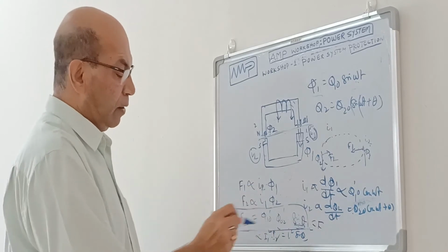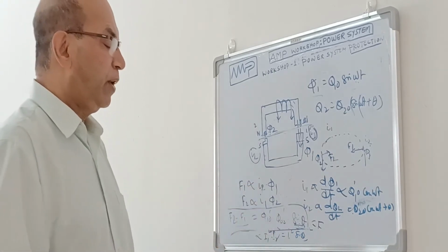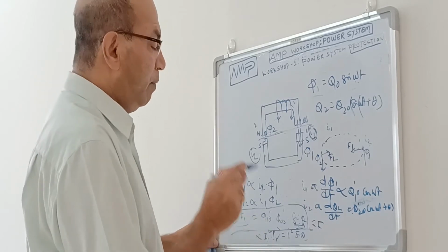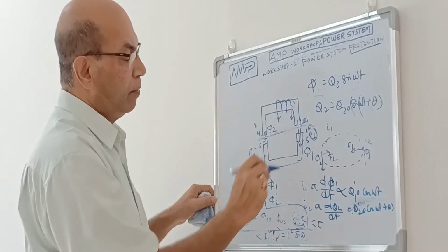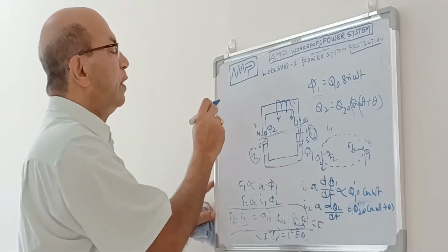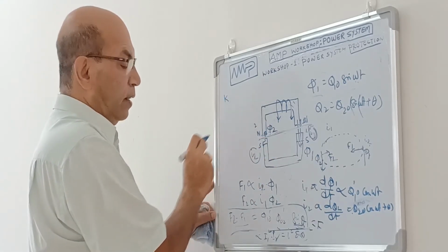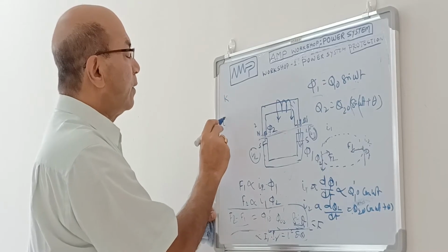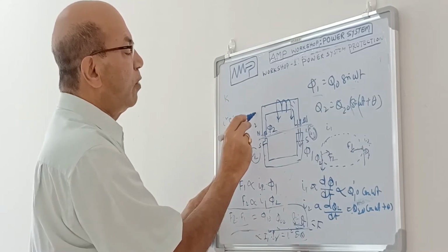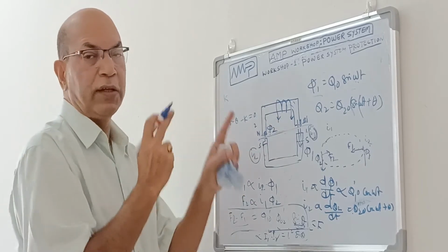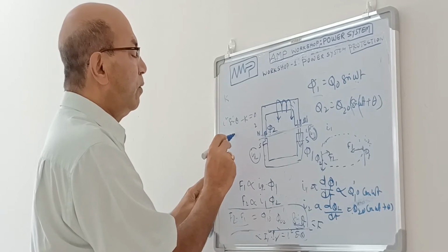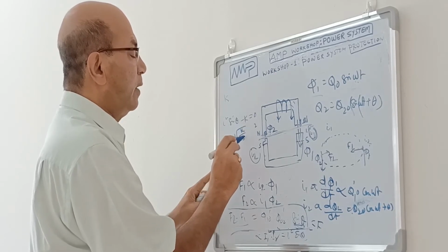So this force depends on the peak value of the current. Now if the resultant restriction, that is the friction force and the pivotal force, is K, then when I square sine theta minus K equals 0, only then will the disc start rotating. So at the stationary condition, I equals root of K by sine theta.